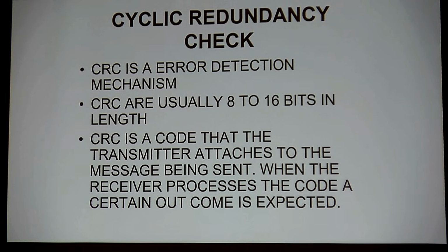This is going to make a polynomial. Now, a polynomial is just a mathematical equation, and it's going to divide down to a known quantity. And it actually comes to where we divide it down to where we have 2 strings of data, and we compare these 2 strings, and if they're not the same, we had an error, a bit error. Okay, so that's sort of the way that that's going to work. The idea is cyclic redundancy is only checking the message. If we don't confine or do anything else with it, it's just checking it to say, is it good or bad? Because we don't want to have a message out on the bus that was bad, because if you said that you're going 200 miles an hour and you're going 30, we would have some type of an error.